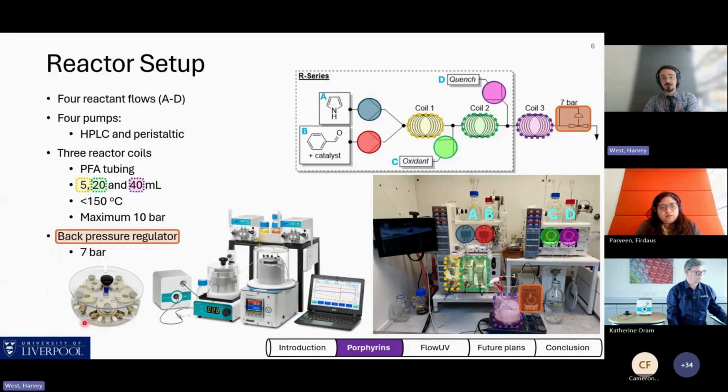As my colleague Firdaus mentioned as well, we can work with devices called continuous stirred tank reactors, or CSTRs, where through the use of wider bore tubing and a cascade of small tank reactors, we can achieve a really quite tight control over our residence time distribution and negate some of the common issues with flow chemistry of blockages or solid materials, say, crashing out in solution.